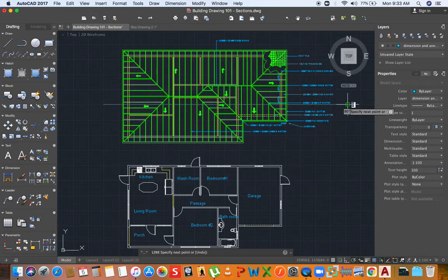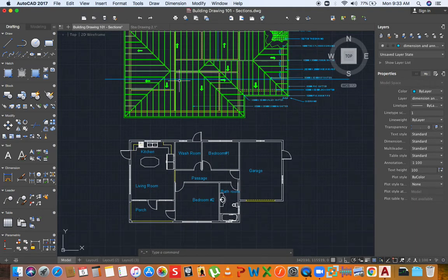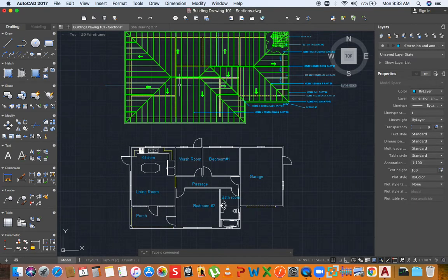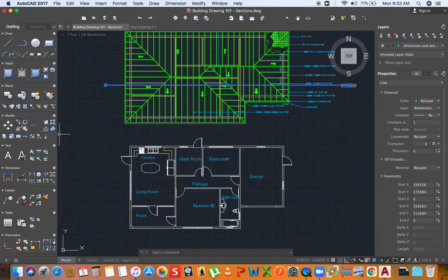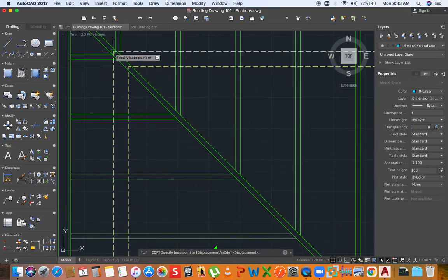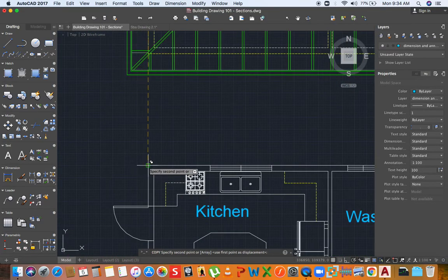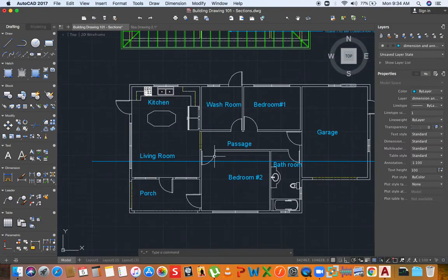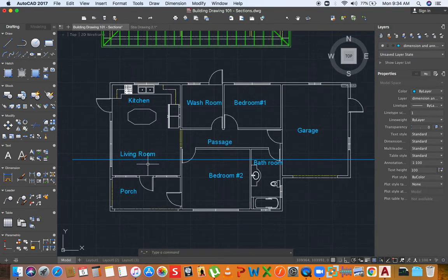There are a few things to note when trying to choose a point, like how it will affect the roof. So if you cut it here, everything behind this portion you will see, anything in front you will not see. So let me copy this point to the front view. I'm copying it from the top edge of the building, dropping it at the top edge, and it will cut through the bathroom, the living room, this window, and this wall, this wall, this wall, and this wall.